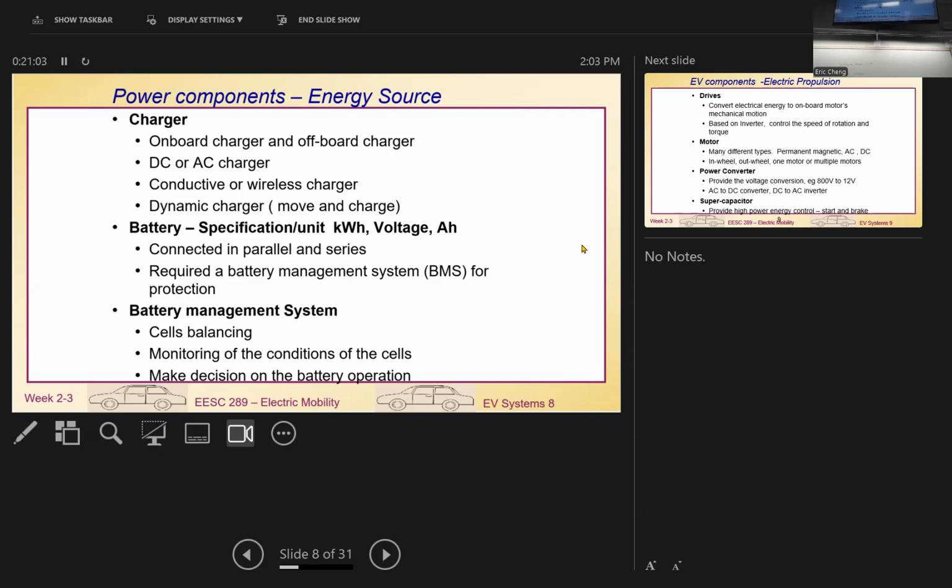Too close to each other, and you may end up with some other problem, because the bottom of your vehicle is quite distant from the ground. So that means your coil cannot be put close to the ground, otherwise you damage it. So you can't just keep moving the coil up and down. Some systems, when they designed it, got an actuator motor. When they park the vehicle, they lower the coil, touching the ground, right? Then they may think that would improve the efficiency. When they finish charging, they use a motor to lift up the coil. Do you think that would be a good design? No, you don't like that. Parking a vehicle, I like it to be convenient.